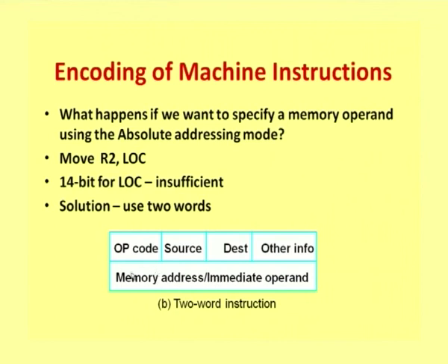Okay. So, in this case, for instance, if this whole thing was a 32 bit word, I now have provision in this instruction format to specify a 32 bit address, which means up to 2 to the power of 32, which is 4 gigabyte of memory locations, can be specified here. Okay. So, this would give me a 2 word instruction. Now, remember, one instruction does not get over in one word, but I will have to use 2 words for the instruction in this case.